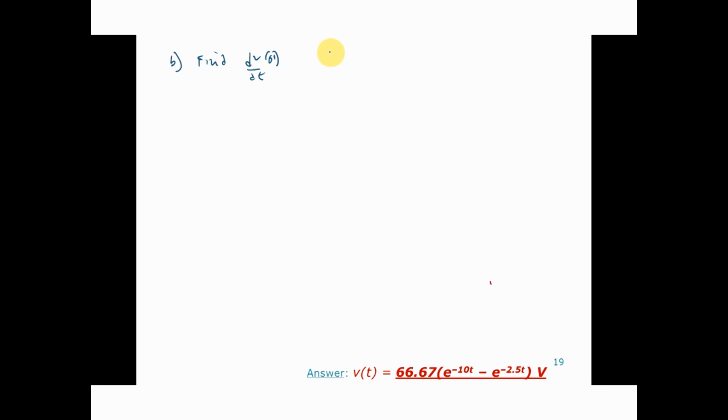Now the capacitor law says that IC equals C dV dt, right? And so therefore, dV dt at 0 plus is just going to be IC over C, where you take the IC of 0 plus. So if we can find the current flowing into that capacitor at 0 plus, then we can find the slope of that voltage.